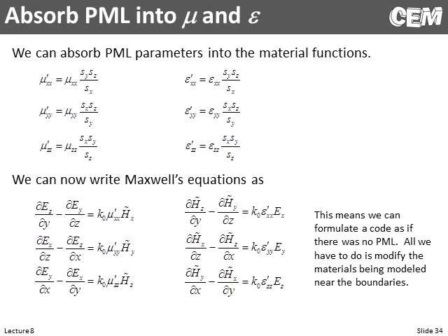One of the reasons that I like the uniaxial perfectly matched layer is that it lets me formulate, code and test an entire algorithm without considering anything about a PML. I just build in ordinary mu's and epsilons. I can test it, get it working. And then all I have to do to include a PML is, right after you build the device on the grid but right before you model it, modify your mu's and epsilons to build in the loss on the outside. So you add one little segment of code, and the same code that you wrote before, not considering anything about a PML, suddenly has a PML. That's really simple, and that's how I like to do it.